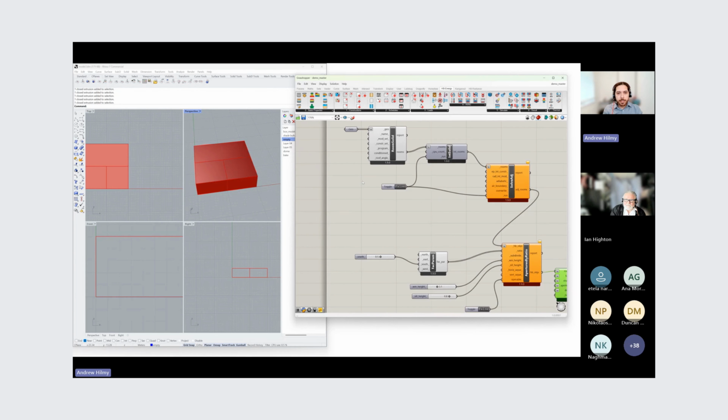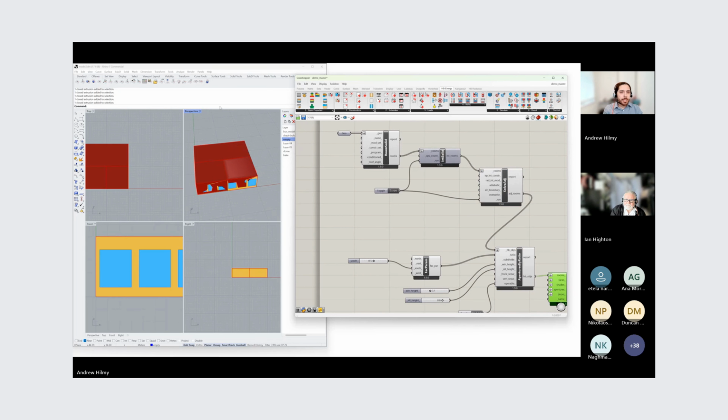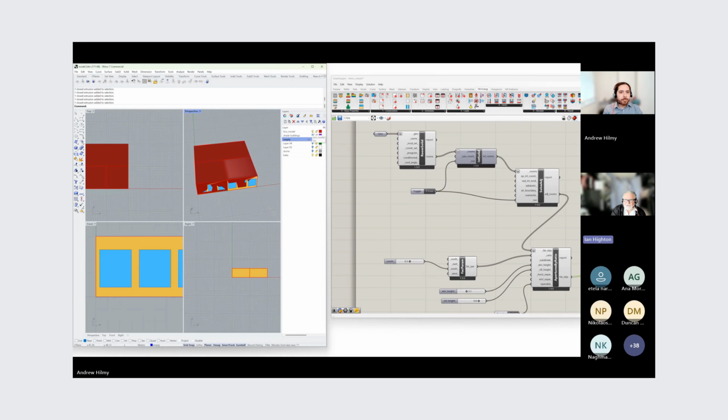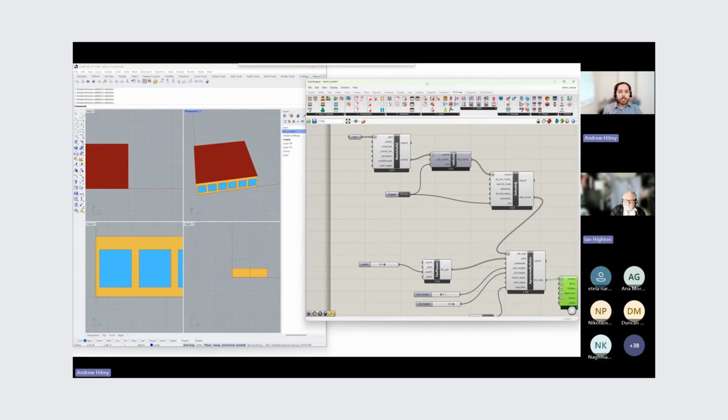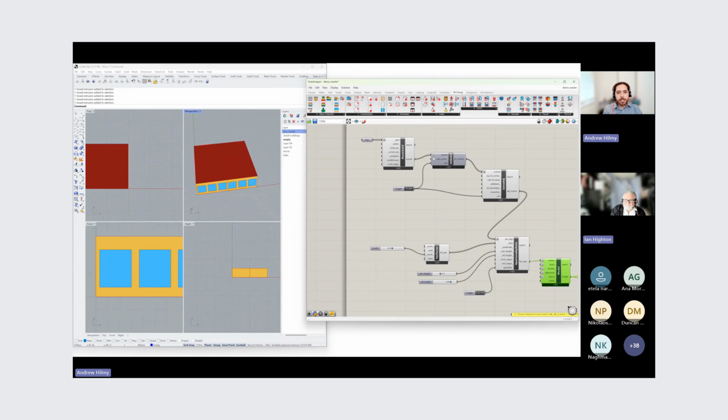So if I turn this on and hide, IDF's preferable because that's also got the construction and internal condition stuff in it. Is that right? Yeah, exactly. So even though GBXML can specify construction information and internal conditions, if you use the IDF route, then that comes automatically into TAS. But from a geometry point of view, the two are very similar. But yeah, the IDF is advantageous if you want that extra information to come across.